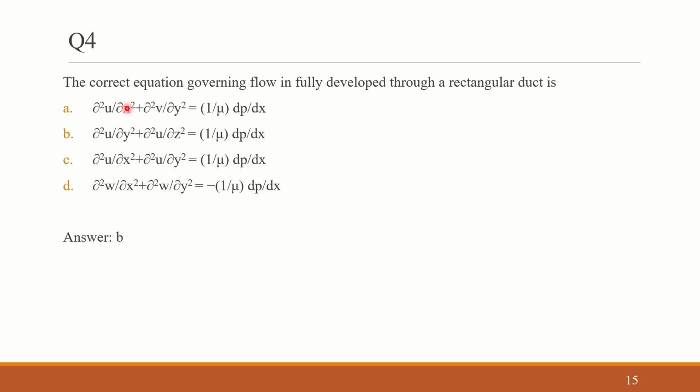On that basis, by reading the question itself, you can reject certain options. For example, it is an x directional flow, so you would be knowing that only that component varies with respect to y and z. If it is u, it would vary with y and z, and therefore there would not be any variation in the other two. So v and w will be 0 for this particular case, actually not for everywhere.